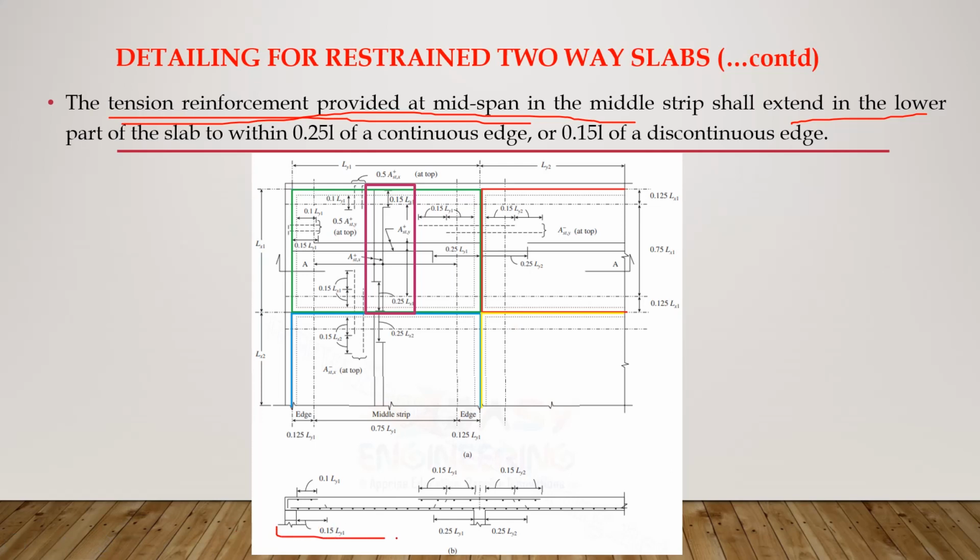if you look at this figure, it may be small for you, but I think you can see it clearly. There are bars on the bottom which are seen as dots here, and these are bars in the shorter direction, because we saw in our previous slide that the bars in the shorter direction are kept below. The long line drawn above these dots is the rebar in the longer direction.